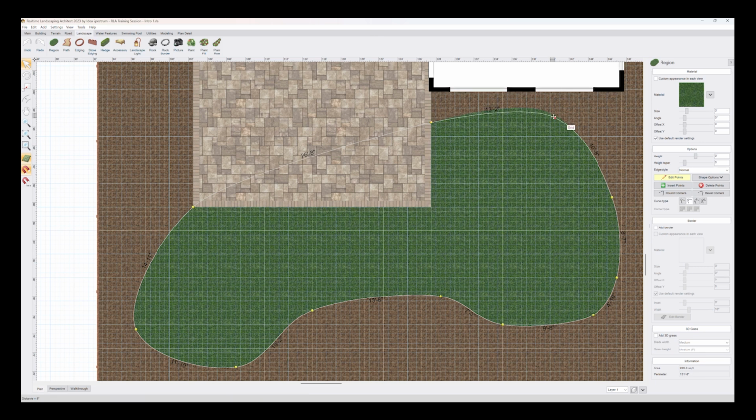This one here, we want to drag along the same grid line over to the side, but we don't want this curve at the top. So what I'm going to do is select angle, the right angle there, so that that's a straight line, but then continues to curve outside. So when I click on this one, you'll see that it defaults to the curved one, and this one is the angled.